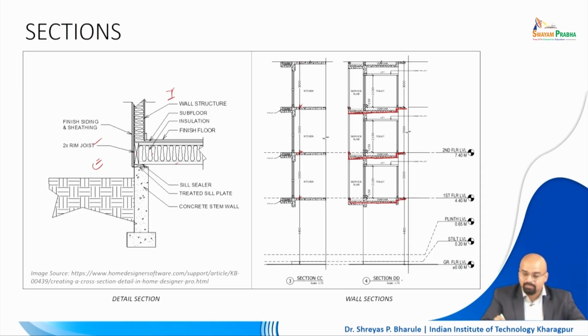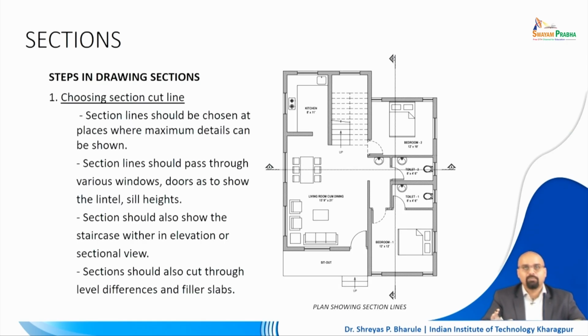Along with that, there is a filler on top of which the tiling is done. So all of these details can be clarified: how deep the sunken pit is, or how thick the filler just below the tile will be, is all clarified with this kind of section which is drawn, right? So a wall section is quite important.